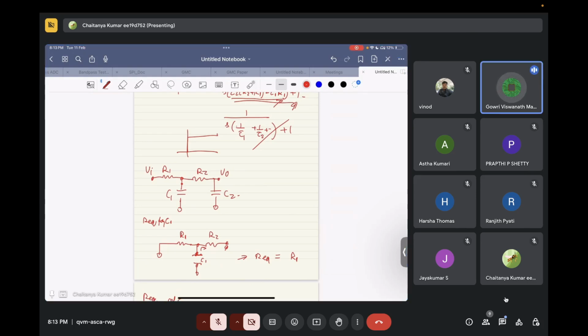For inductor, it is quite opposite. Yeah, correct. For inductor, it is opposite. A slight amount of intuition you can get is that since we are anyways interested in very low frequencies, at low frequencies the capacitances are mostly high impedance, right? At DC and at frequencies closer to DC, the impedance of the capacitors will be very high. So basically, you will open circuit all the capacitors and short circuit all the inductors.